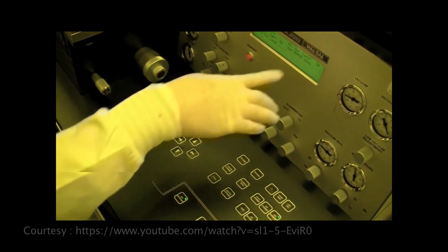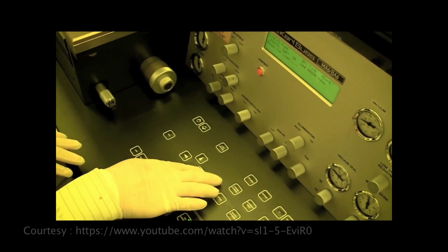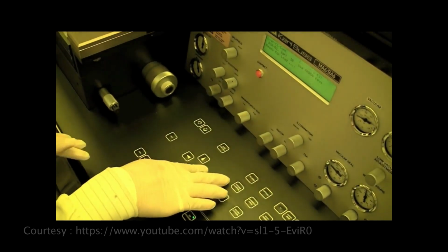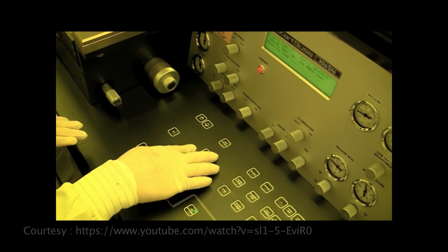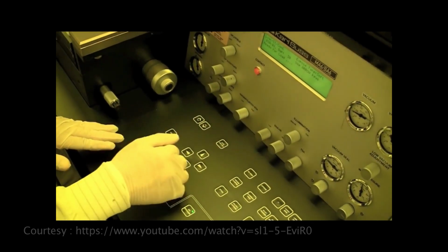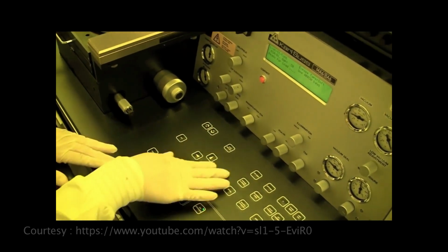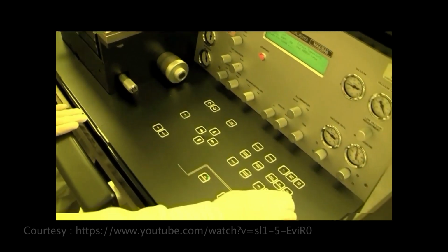Let's change the alignment gap. Let's make that 40. And then let's change the type of contact. We'll make it soft contact. And now the parameters have changed. There's different types of exposure types, from soft, vacuum, hard. You can look at the supplemental to get more information. But right now we'll set it as soft. So once your parameters are set, you can hit edit parameter.